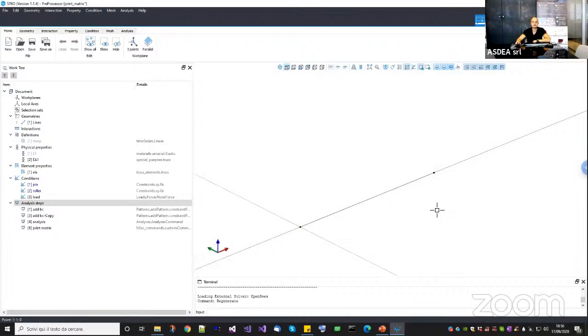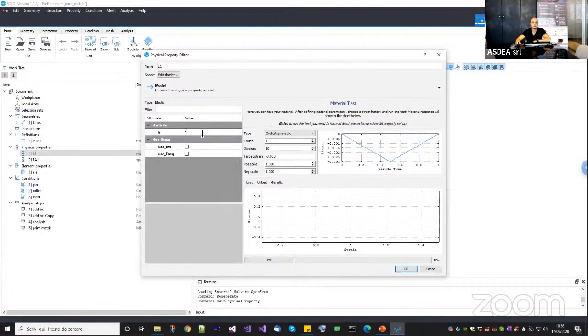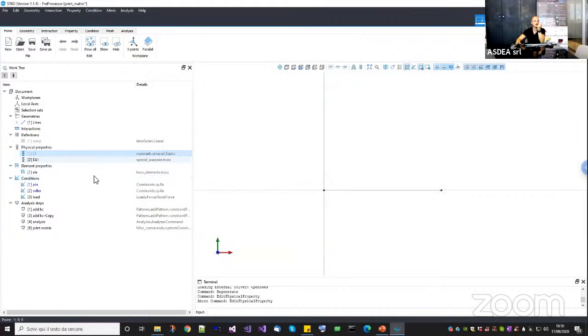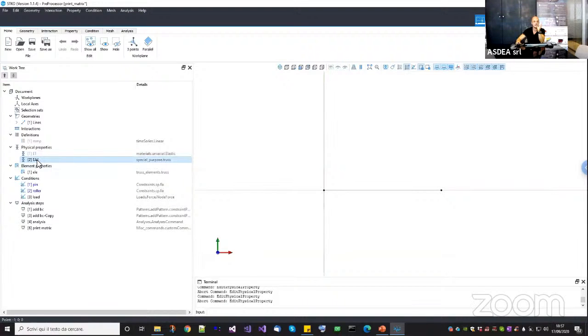This file is very simple. You have just one truss in the middle, which is this one. Okay, one line, one truss. Then you have a ramp here. Then to make it very easy to understand, I created a uniaxial material with a unit Young modulus and a truss section with a unit area, so that the EA, the actual stiffness of this one, and the length, of course, is 1. So EA over L is equal to 1. So it's very easy to visualize the stiffness matrix.